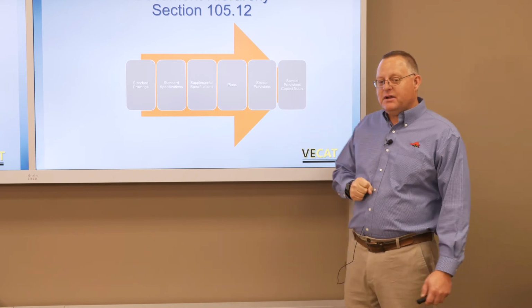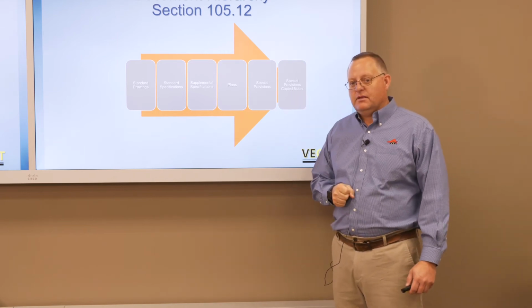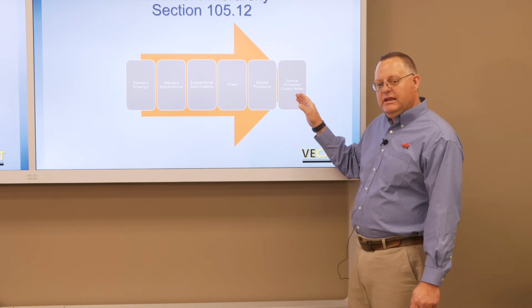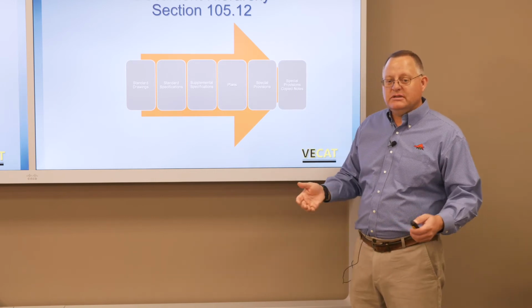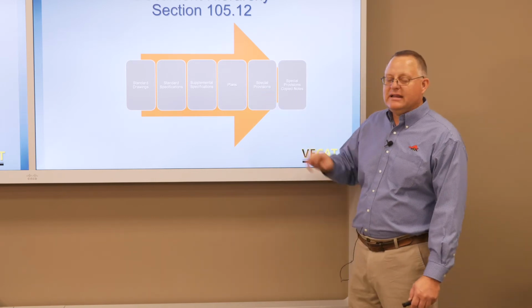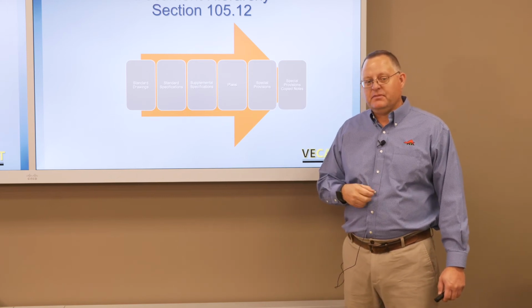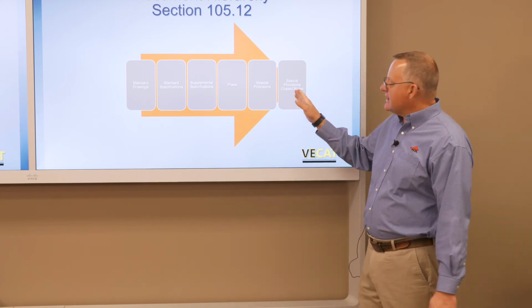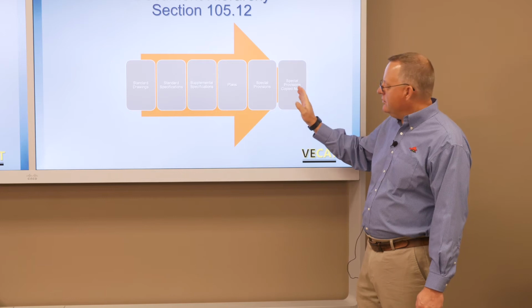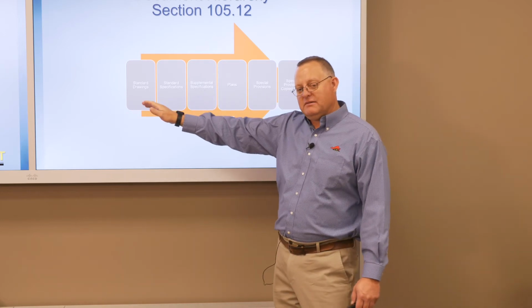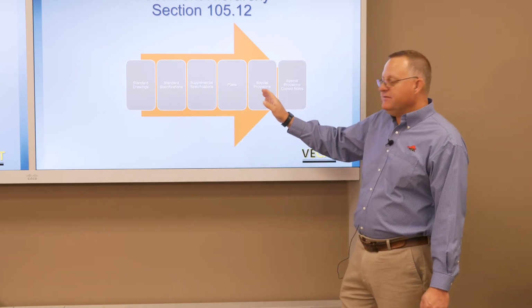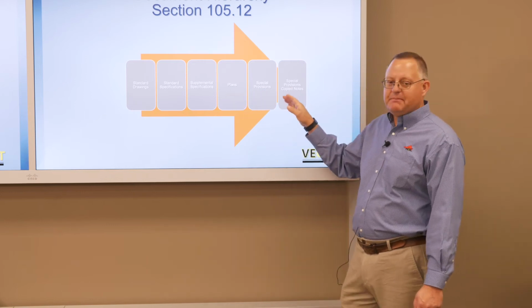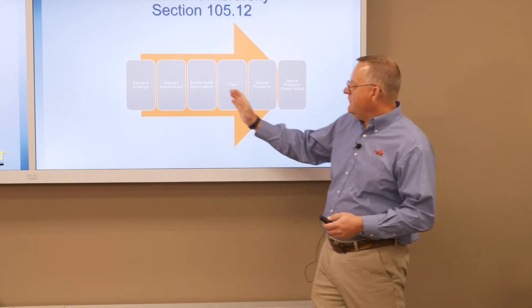And then we have some special provision copied notes. So maybe unique to a certain project or a certain district that may rewrite a little bit of that special provision. The thing to keep in mind is the copied notes are the highest level and they override everything below it. Special provisions override everything but copied notes, and so forth and so on.